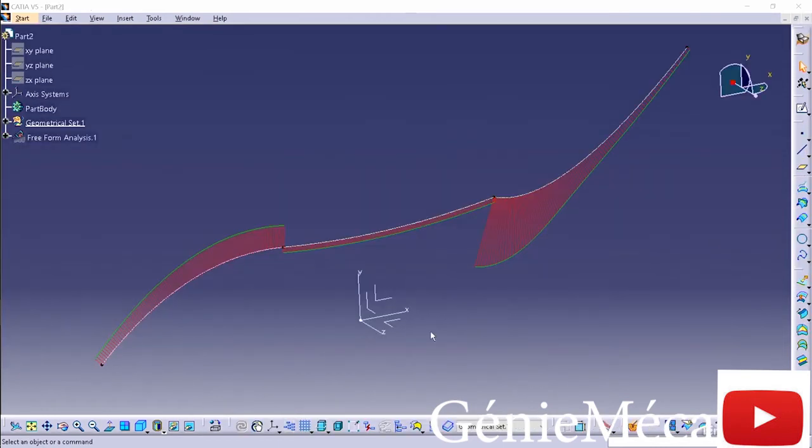I'm going to be talking about continuities, and I'm going to use curves to show you what a continuity is between adjacent elements. And this is the same for surfaces. It's just easier to show using curves. I'm also going to use a tool called porcupines to really show you exactly what's happening with those continuities. So we'll be talking about these tools later on in the course, but I'm just going to use them here to show you what continuity means.